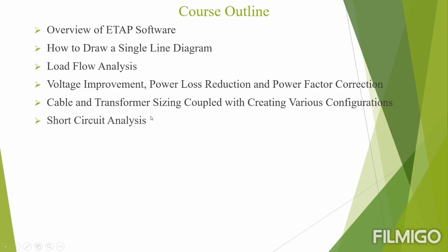After that, we'll enter short circuit analysis, where we have to determine the magnitude of fault current flowing through different bus bars, the maximum and minimum amount of fault current, in order to determine appropriate ratings for our protective devices.